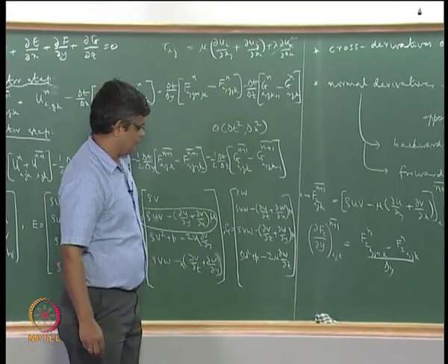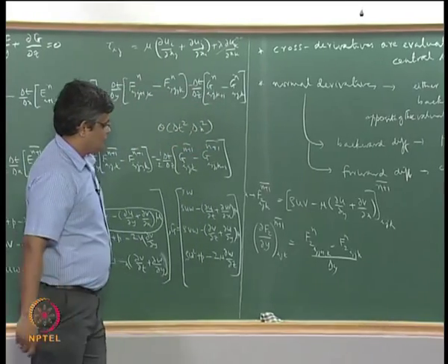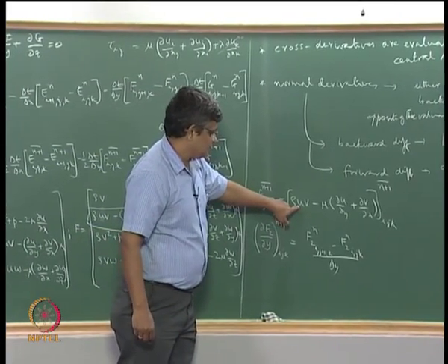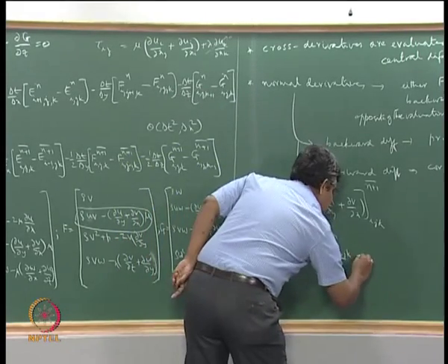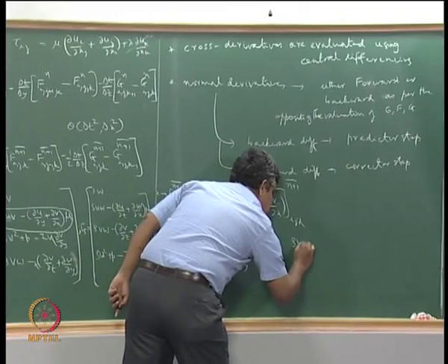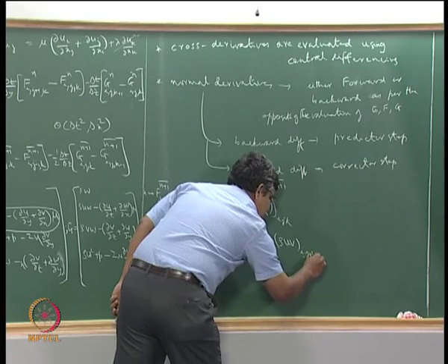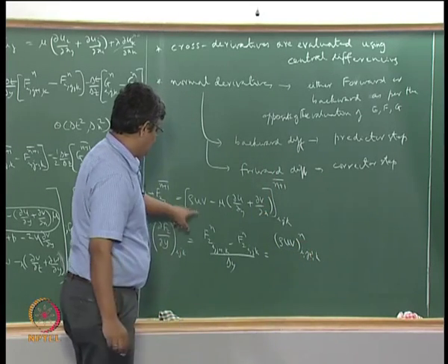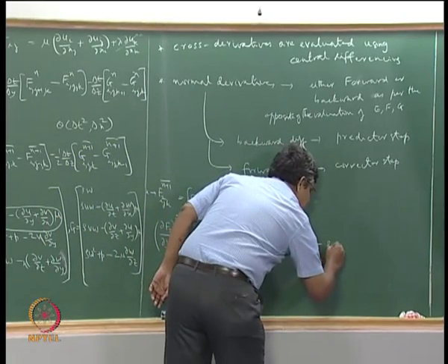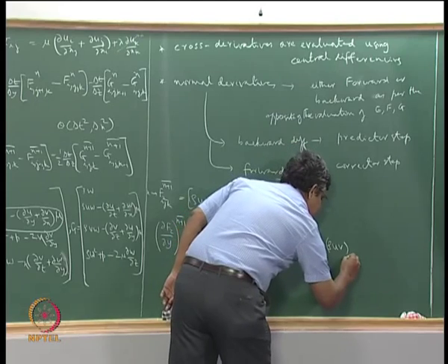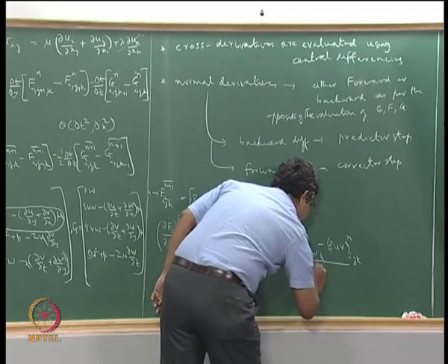It is forward differencing. Now this f2 here has each of these components. For these things it is straightforward, so we can write the corresponding component of each of these, and we can say that this means rho uv at i, j plus 1, k, n is this one, if we consider only the first term here, minus rho uv at i, j, k, n, by delta x.